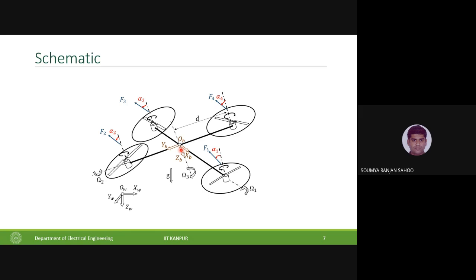So what is happening here is, to control the XY position, the tilt of the rotors is being controlled, because this tilting can generate a component in the horizontal plane, and the vertical components are anyway there. By controlling the vertical components, you can control the roll, pitch, yaw, and the Z, or the height or altitude.